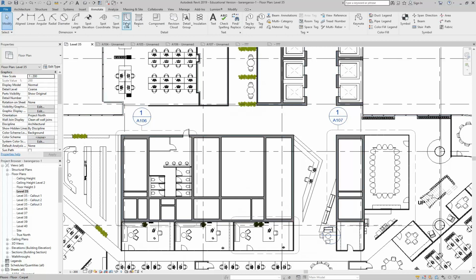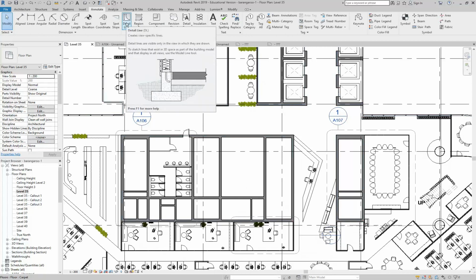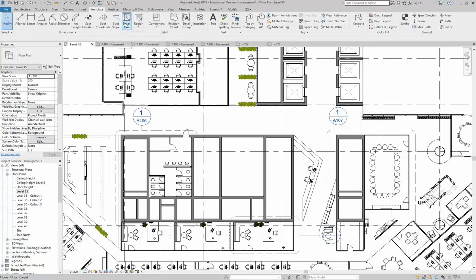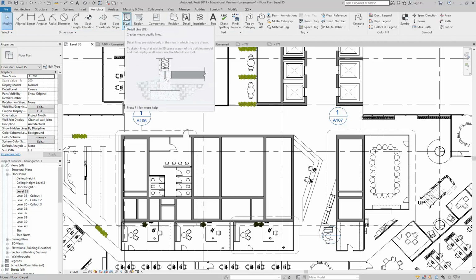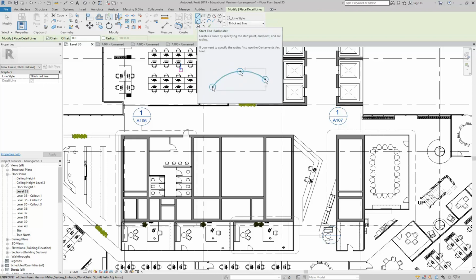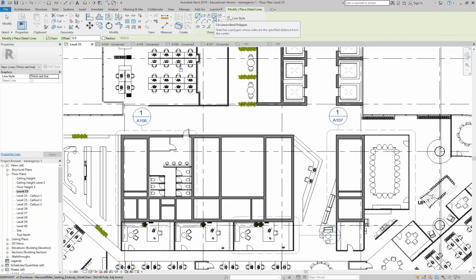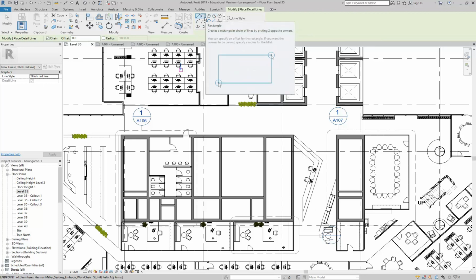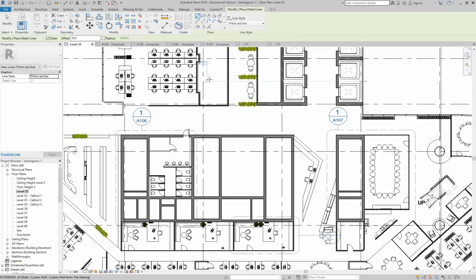So here, once you start documenting things in Revit, now that you know AutoCAD, it will become crystal clear to you how it can be used to improve your productivity. On the Annotate tab you've got all the detailing tools, and we're going to get onto this. The drawing tools, say things like detail lines, are much slower than the drafting tools in AutoCAD. So you might be thinking, why am I going to use Revit to draw when I can draw much faster in AutoCAD? But it's the management, updating and revising of things that is much better in Revit, even though the initial drawing is slower.